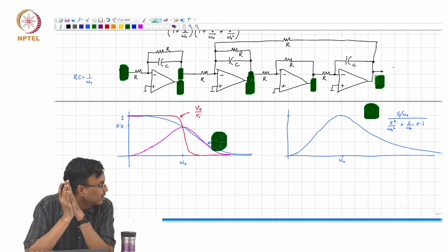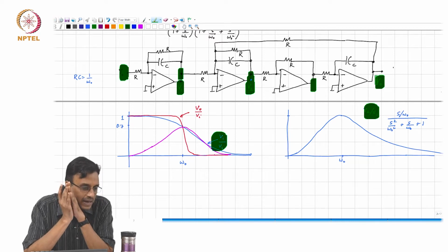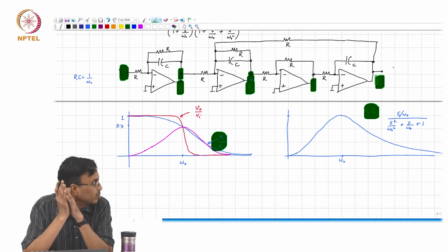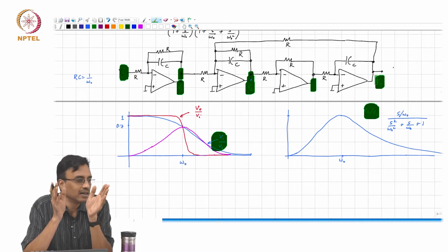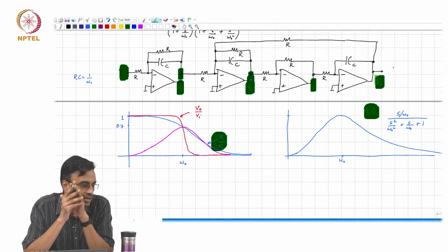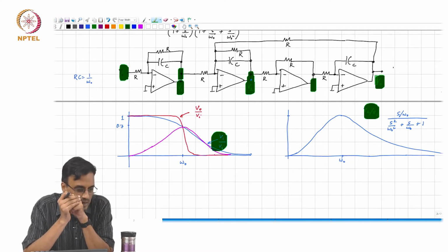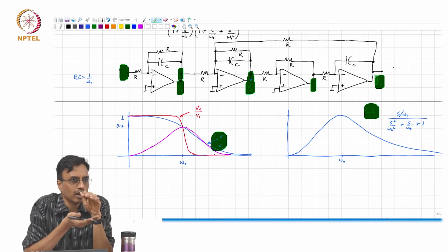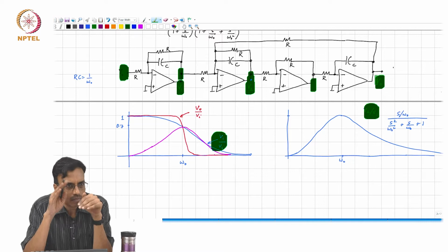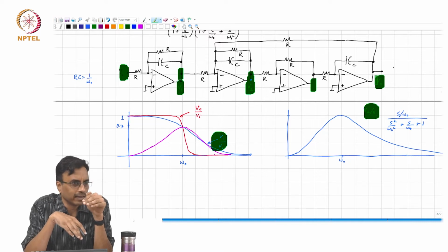Remember that the op amp being ideal and the virtual ground being a short and all that is only valid under the assumption that the op amp is in its, within quotes, high gain region of operation, and that's only valid as long as the outputs of the op amp don't get too close to the positive and the negative supply rails.